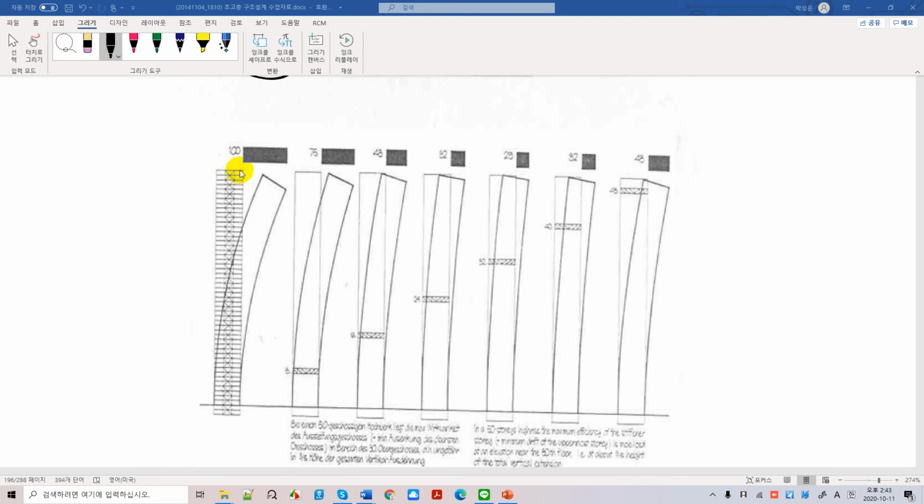To me, if these frames support lateral force, then we call that, yes, a dual system. If the frames out there do not support lateral force because the frame is built based on simply supported conditions, then we call that a building frame. Either building frame or dual frames, I have no idea, but such high-rise buildings are probably built with a dual system. That's what I guess. And you have the outrigger's locations varying from here all the way to here.